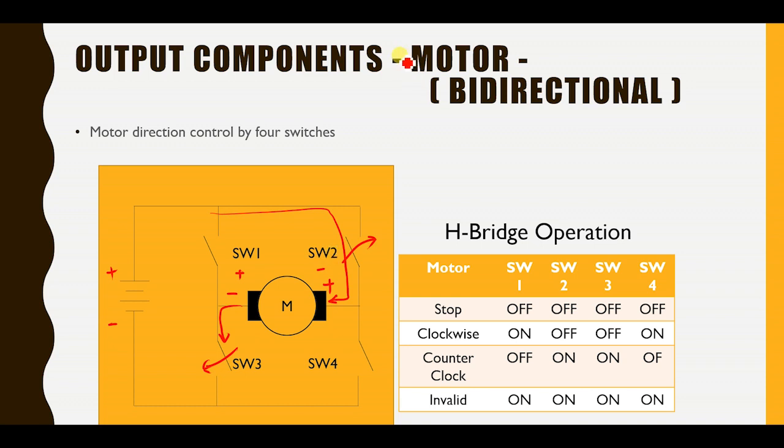So it depends on the switch position. This technique is already easily implemented using H-bridge operation. You can have a truth table here. H-bridge will control the direction of current through the motor.